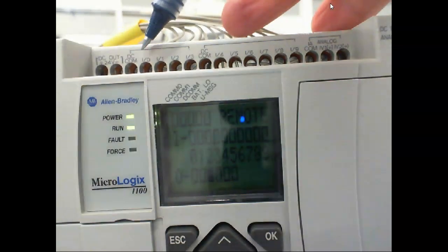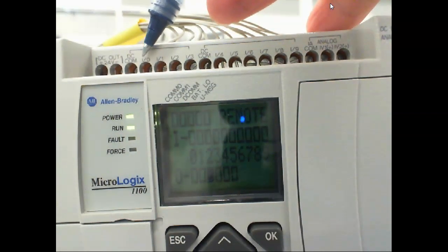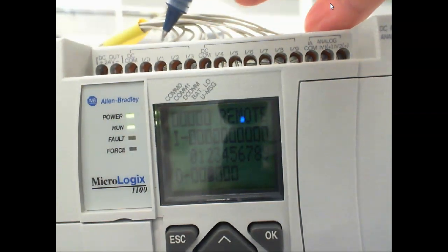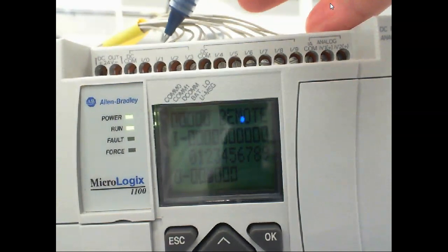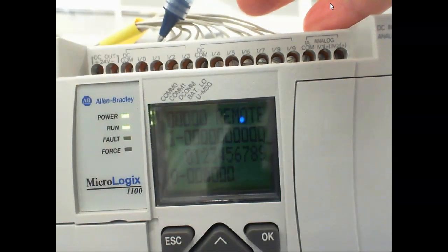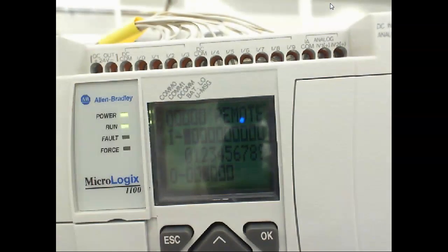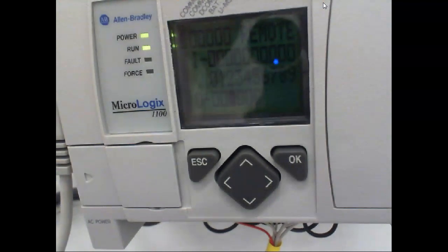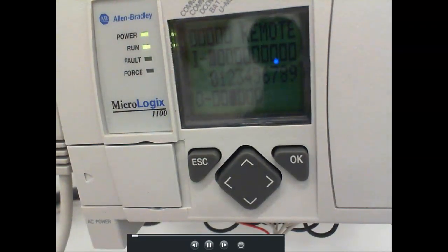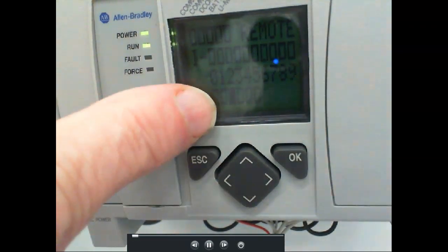So if I wanted to address whatever I have connected coming in on this wire right here, it's going to be one of these switches down here. In fact, it's going to be this switch right here. Then I would assign it this address. I don't know if y'all can see. I'm going to come over here, and this is what's nice about a PLC.